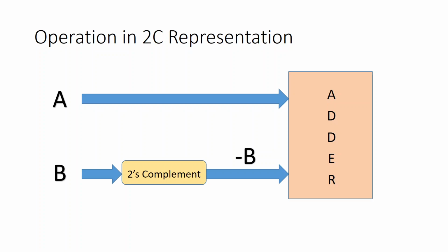We don't need a subtractor if we are dealing with complement representations, because the adder can add the 2's complement of b, the number to be subtracted, and the result we are getting here is the 2's complement representation of a minus b. Then we have to simply do the interpretation of this 2's complement representation number. That interpretation can be dealt with by another circuit, or the receiver can interpret it in its own terms.